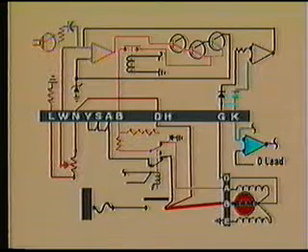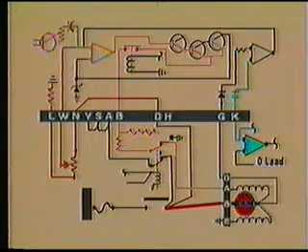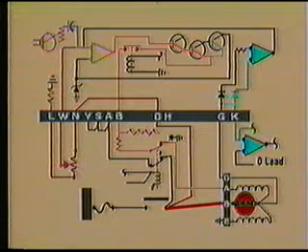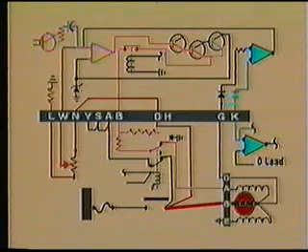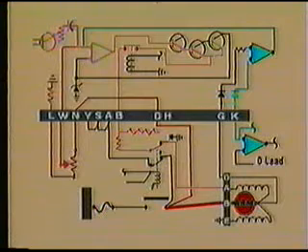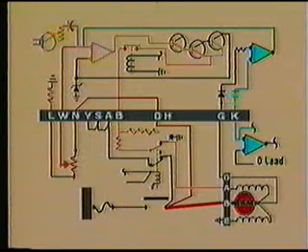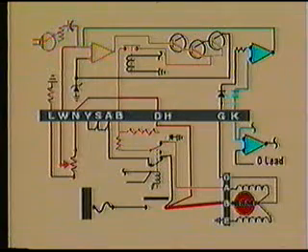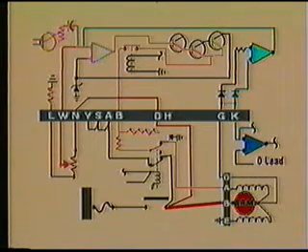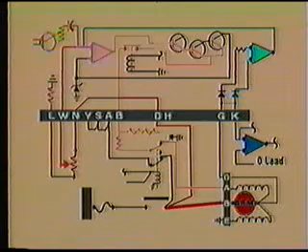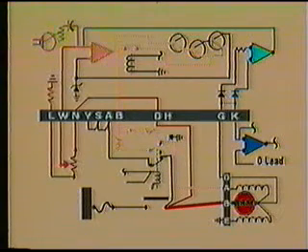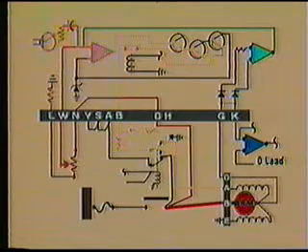Now we place the other generator on the line. The paralleling portion of the system now comes into play. This input will also have the effect of canceling out some of the oscillator output until a state of equilibrium in load sharing is reached. The result of this action will be exactly the same as before. If one generator begins to carry more of the load, the paralleling input to the opposite generator will cause the A-lead current for its generator to increase.